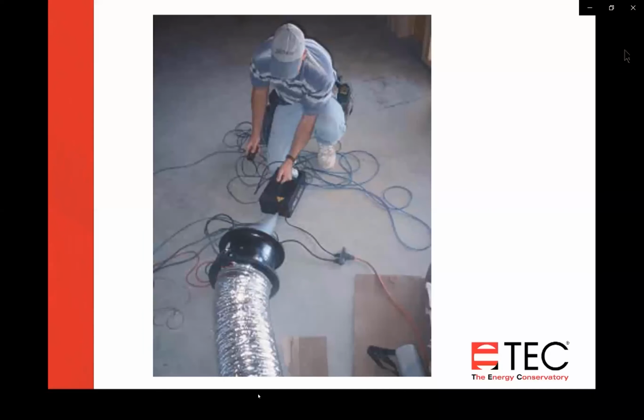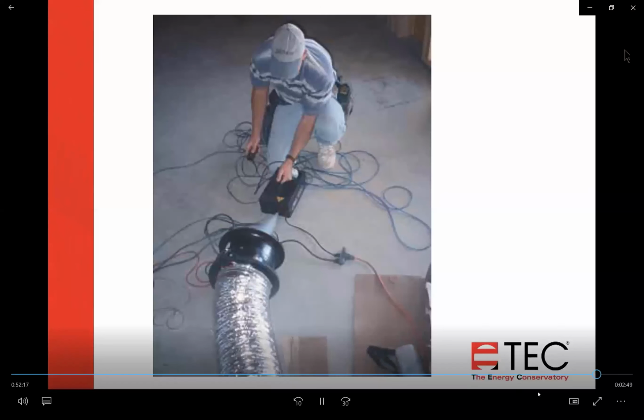We have seen fans come in for repair where people have been using a smoke bomb or something like that, and those are very corrosive, and they'll tear apart the electronics. They'll eat up the electronics pretty good, and now you're not going to have an accurate fan, or you're not going to have a fan that even works anymore. So you want to use a fogger that has something like a glycol solution that's non-corrosive.